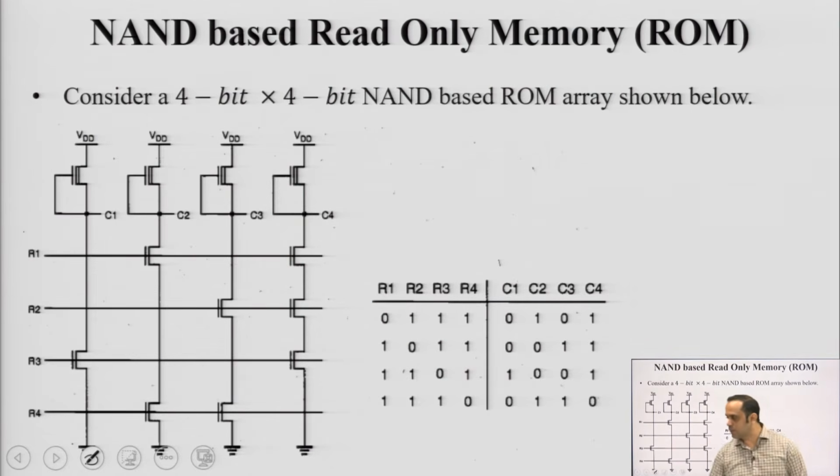Right. Now, consider the counterpart of it, which is known as NAND based array. Why is this a NAND based array? You see that somewhere you can see the NMOS circuits are connected here, and instead of PMOS we are basically using depletion load N MOSFETs. What is a depletion load N MOSFET? Here you connect gate with source, you are basically looking at a 2-dimensional device. So, the requirement for power is reduced, power sources is reduced, it results in a simpler and more compact circuit. Okay. In this case, whenever you want to access a row, you make it equal to 0.